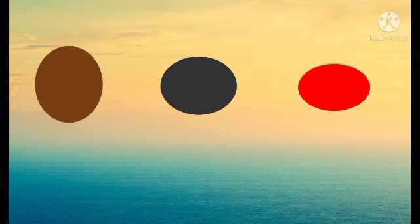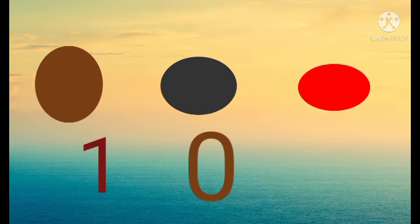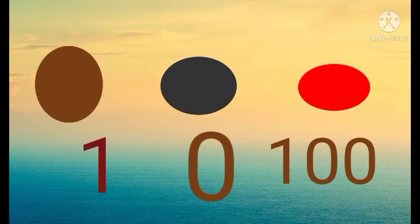As we go through the color code chart of the resistor, the value of brown color is 1. The value of black color is 0. And the value of red color is 10 raised to 2, that is 100, and it is a multiplier.